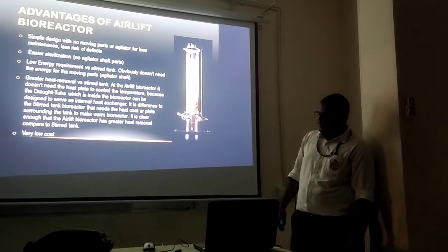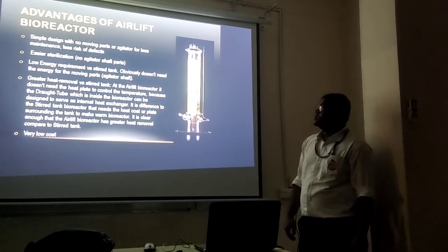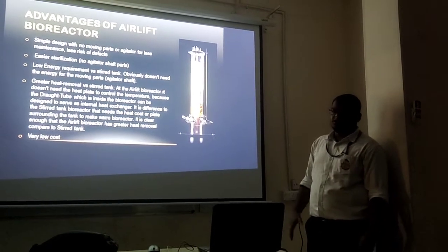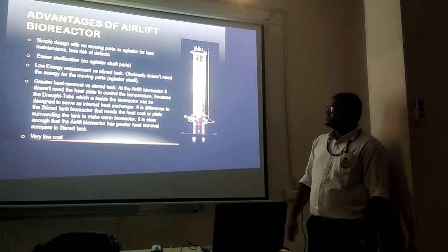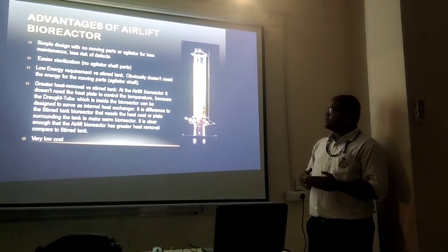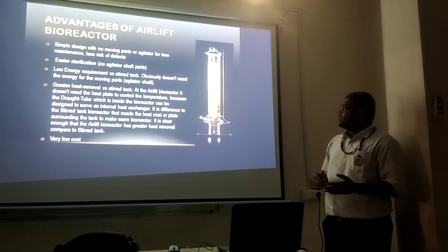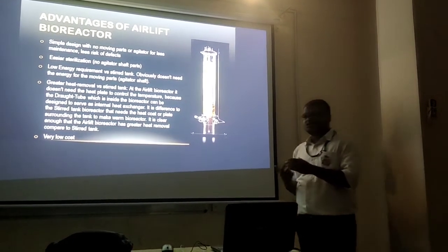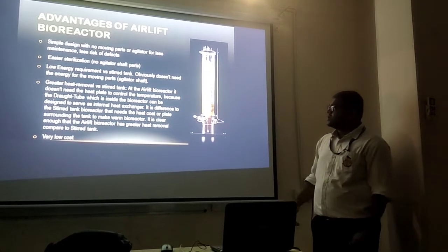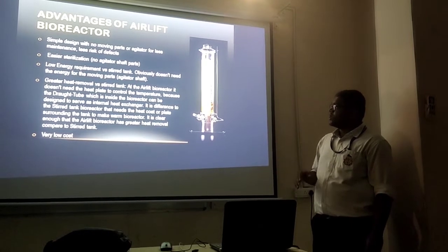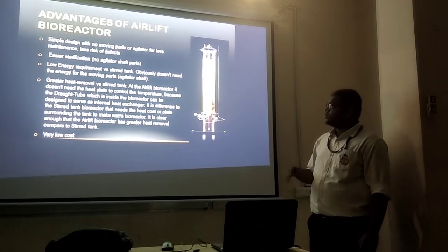The advantages of the airlift bioreactor: simple design, no moving parts or agitator for less maintenance, less risk of defects, easier sterilization, and low energy requirement versus the stirred tank. Obviously, it doesn't need energy for moving parts, as there is no impeller or agitator. Greater heat removal versus the stirred tank, as the airlift bioreactor doesn't need a heat jacket to control the temperature.